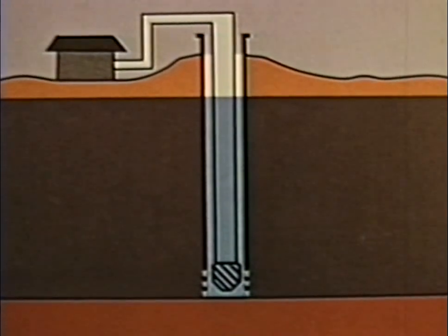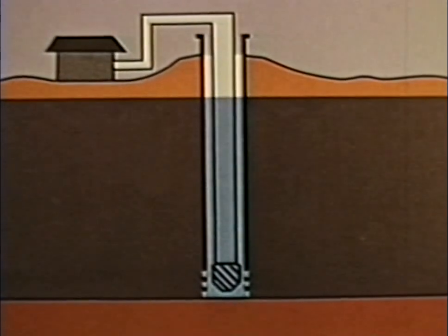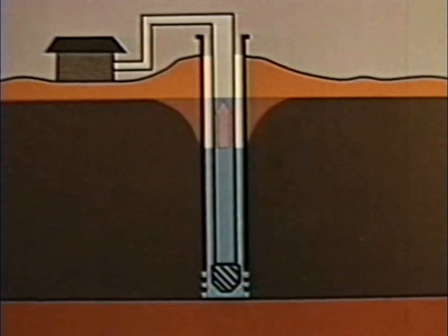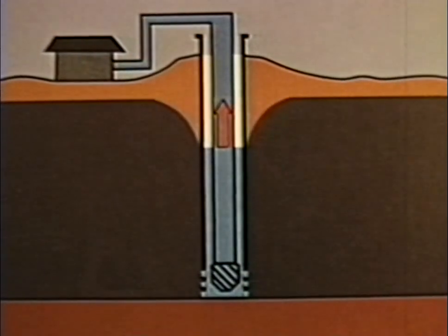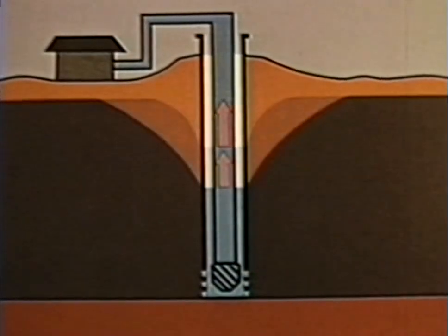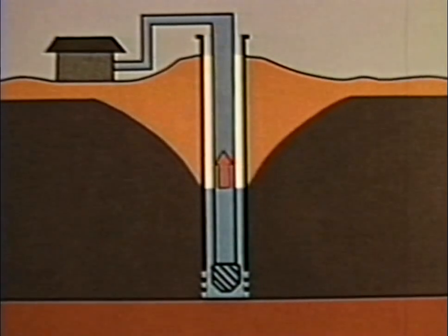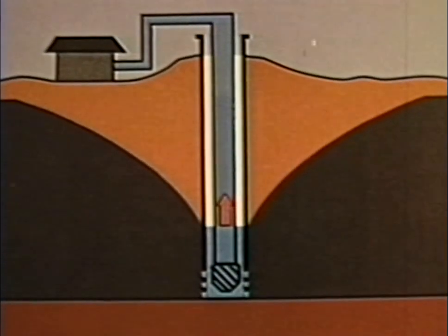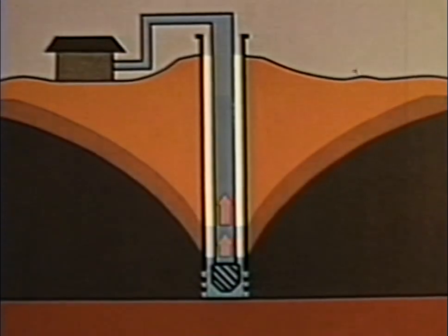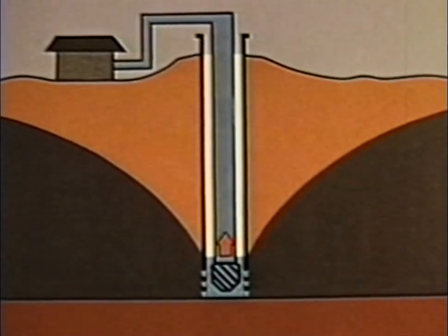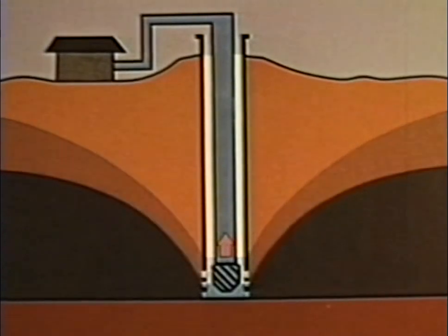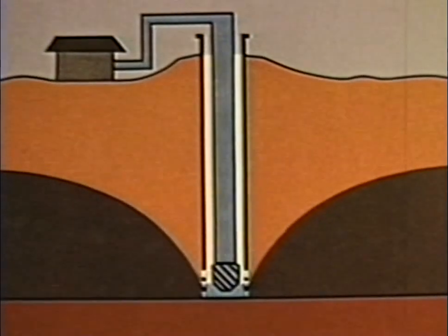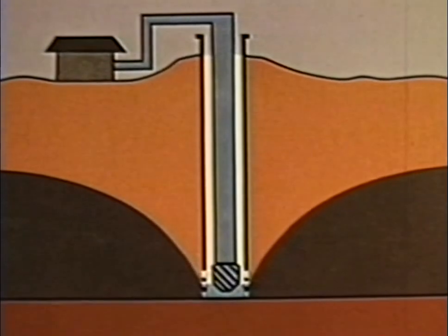When groundwater is pumped from wells, the water levels in the aquifer decline. In this example, the aquifer is near ground surface. Pumping causes drawdown cones to form in the water table surface. Too much pumping causes the water level to decline to the well screen, and the aquifer becomes overexploited.